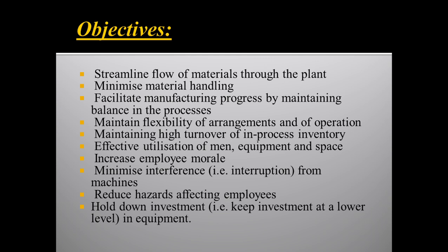Second is to minimize material handling. Then, facilitate manufacturing progress by maintaining balance in the processes. Maintain flexibility of arrangements and of operations. Maintain higher turnover of in-process inventories. Ensure effective utilization of men, equipment and space.